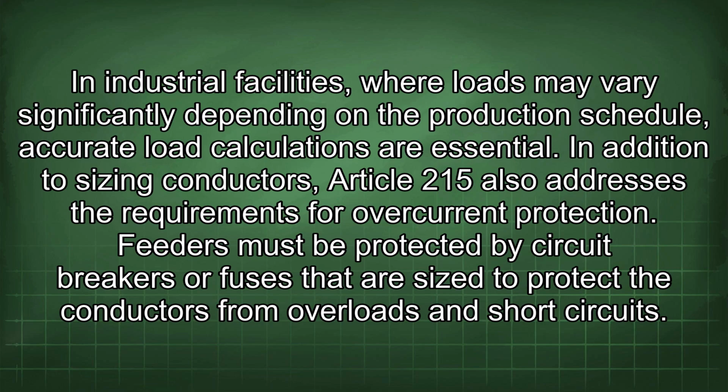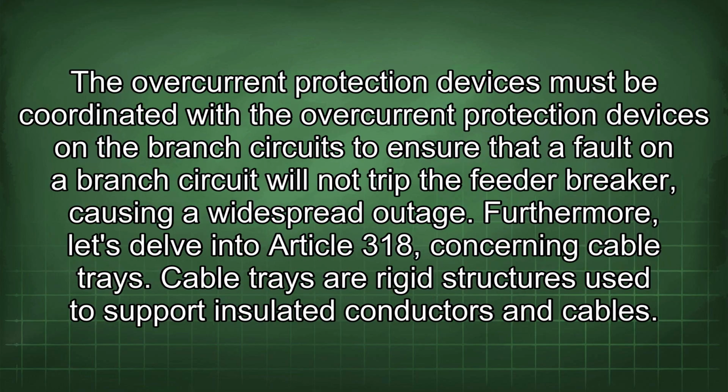In addition to sizing conductors, Article 215 also addresses the requirements for overcurrent protection. Feeders must be protected by circuit breakers or fuses that are sized to protect the conductors from overloads and short circuits. The overcurrent protection devices must be coordinated with the overcurrent protection devices on the branch circuits to ensure that a fault on a branch circuit will not trip the feeder breaker, causing a widespread outage.